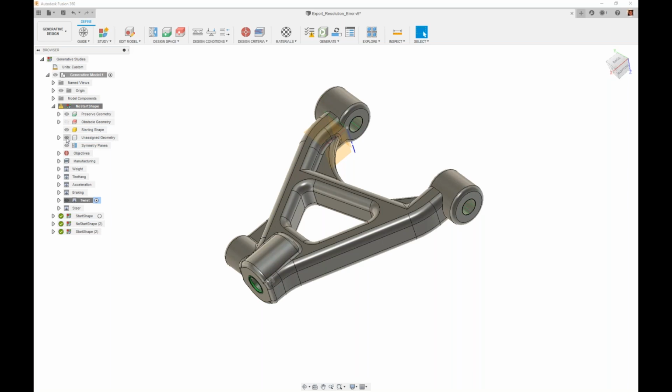And so there is this balance of trying to figure out, and that can also be a variation, right? We have the ability to vary geometry to expand the number of outcomes that we get from generative design. So perhaps instead of using a cylindrical preserve here, what if it was a square preserve, or what if it was 3 times thicker than what I initially drew here?